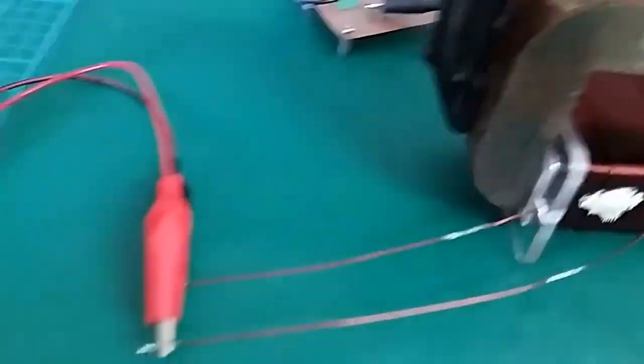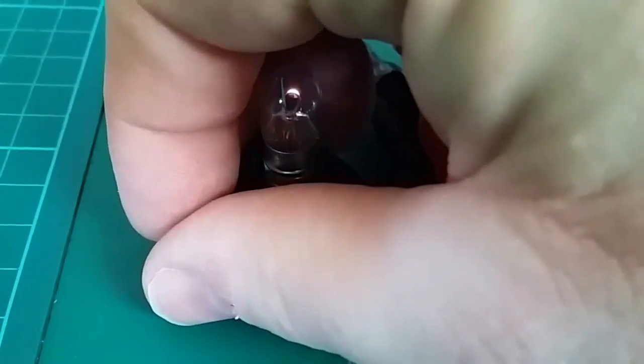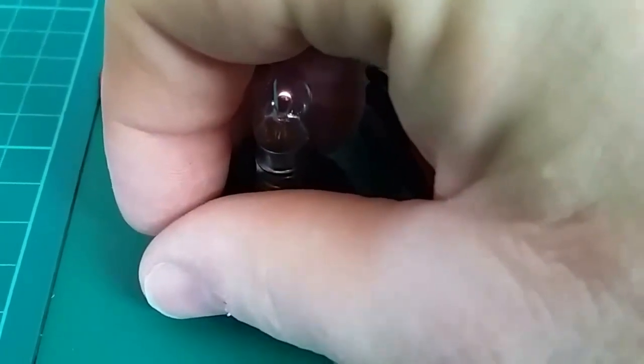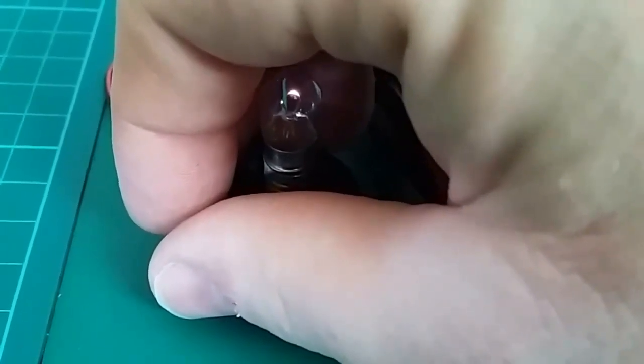So the reason why I wanted to go through it and try and explain this to the best of my ability: you can see the light is not as bright as what we had before, so we're getting a little bit less light. Because remember that we turned down the duty cycle. We went from a 25% duty cycle to now a 5% duty cycle.